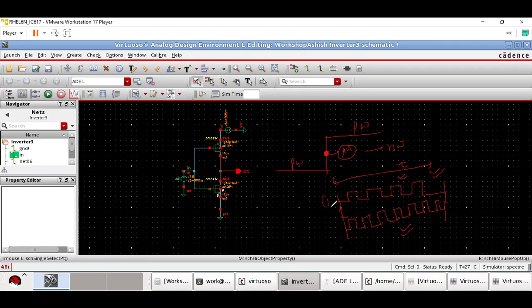Second one will consume more power. Why the second one? Because in more cycles, the switching of NMOS and PMOS is happening. Yes, more switching will be there. And because of more switching, there will be more number of times where PMOS and NMOS will be on collectively. And the power consumption will be very high.